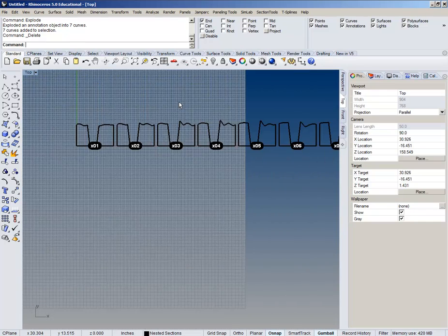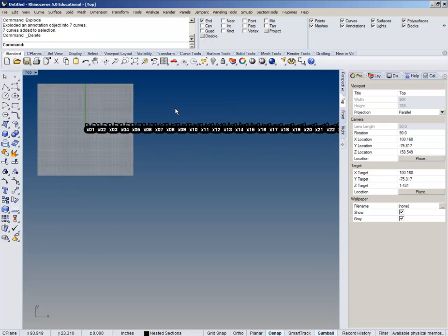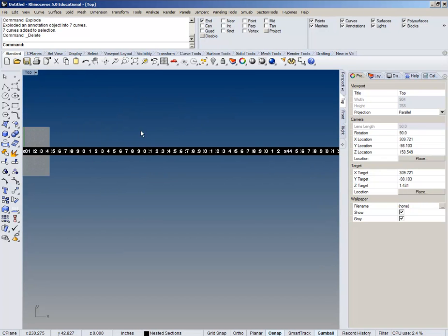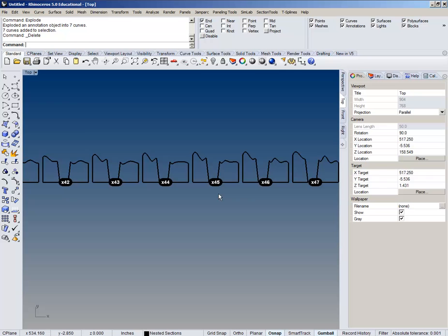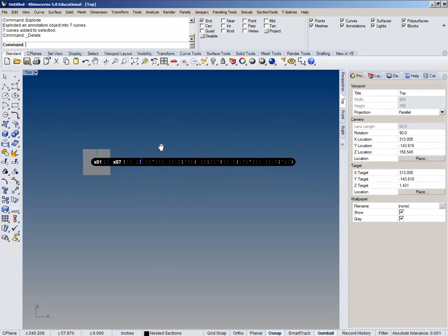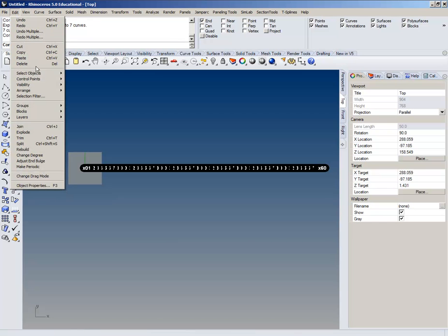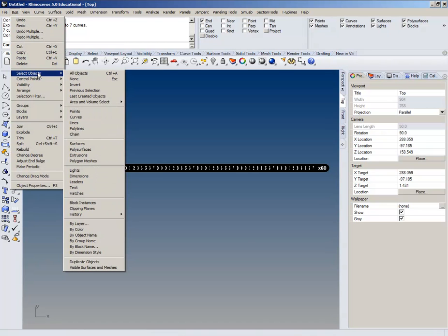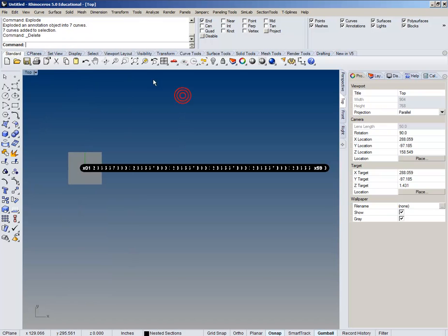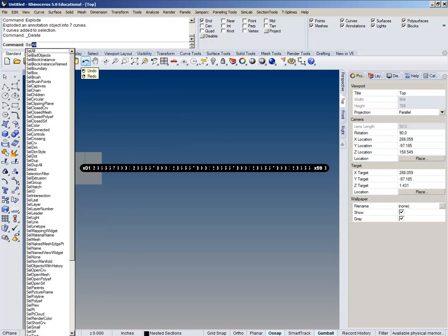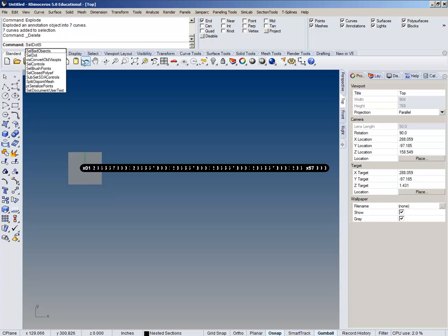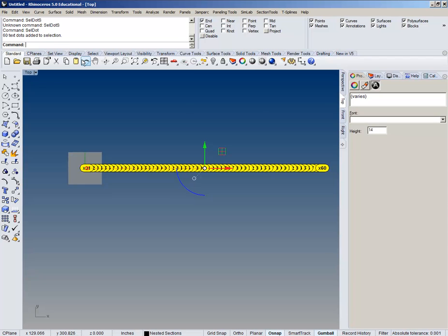It's only by selecting, but before we do that, I've actually got to change the items here to be text. They're dots right now, right? So if I go into Rhino, I can go to edit and say select objects. I don't know if annotation dots are in here. Nope, it's not in the menu. So the command for that is SELDOTS, or actually SELDOT in case you want to just pick one of them.